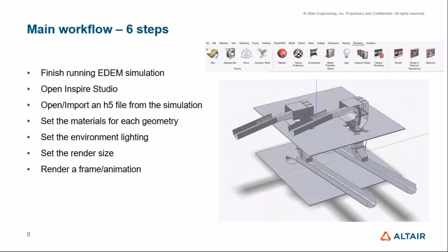Now, the main workflow, and we'll obviously cover this in the demo itself, but it's worth just to give you an idea of, it's pretty much 6 steps that you have to go through. The first one would be a 7th, but because you need to do any kind of EDEM simulation to be able to move on to the other 6, I didn't count it in. So first of all, you finish running your EDEM simulation. Once it's finished, and you do any kind of analysis you want in the analyst, if you want to get a rendered high fidelity visual from Inspire Studio, first thing you need to do is open Inspire Studio. It's kind of a half step, but we'll count it as 1.